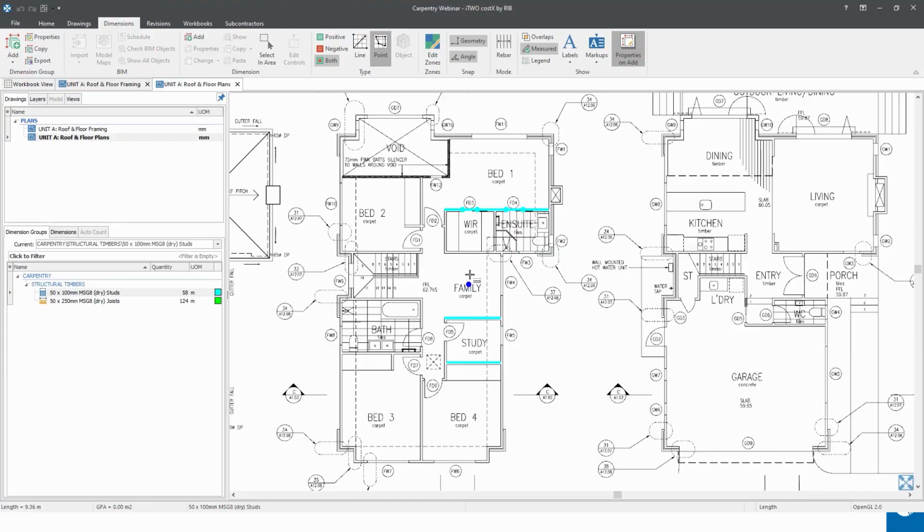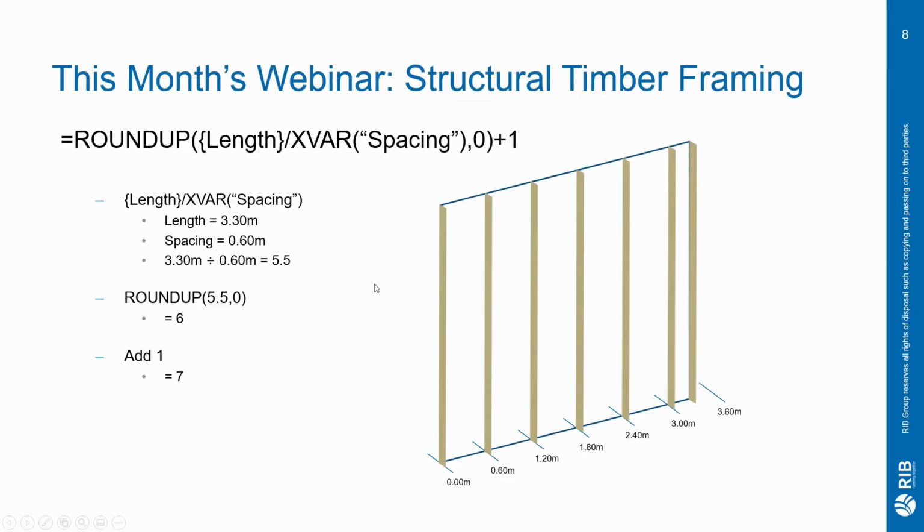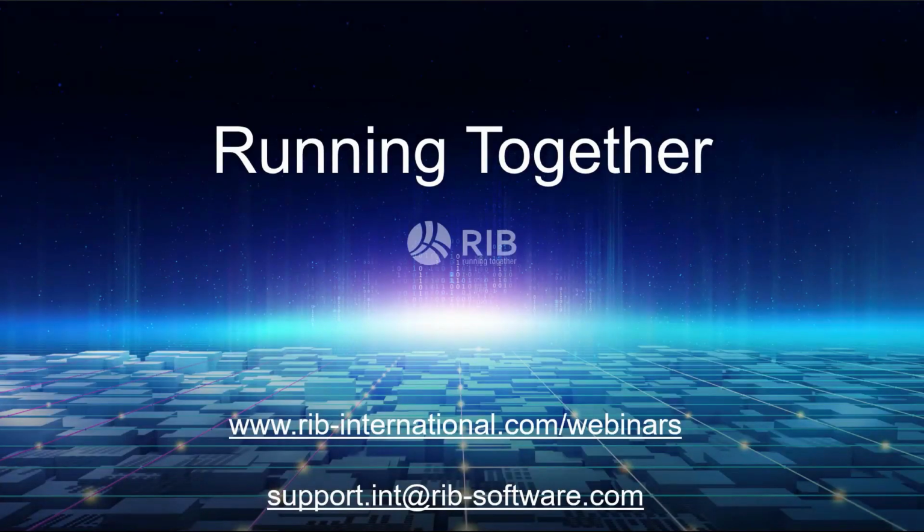Okay, that was fairly short and sweet, hopefully. So ideally what we've covered is measuring horizontal and vertical members, as well as capturing the installed length, which is what is usually done in estimating for pricing, and that's fine for a bill of quantities of many types of estimate. But what we've also got additionally is the merchant sized supply quantities that we need to go and buy from our builders merchants. So for smaller builders and subcontractors doing the carpentry trade, hopefully that is a useful piece of information.